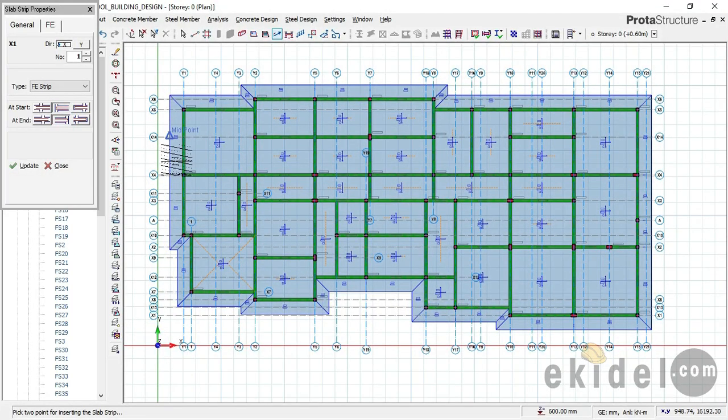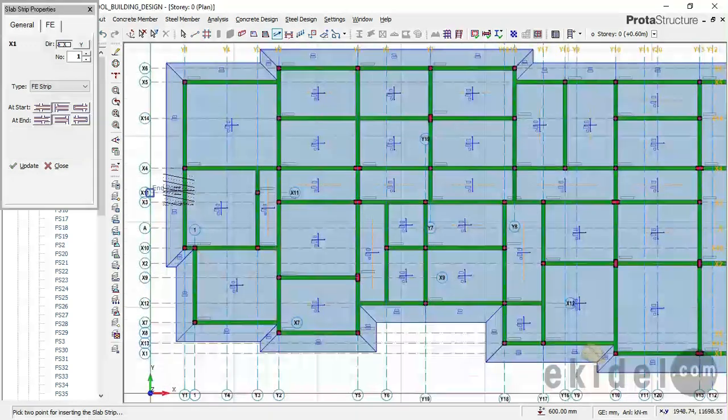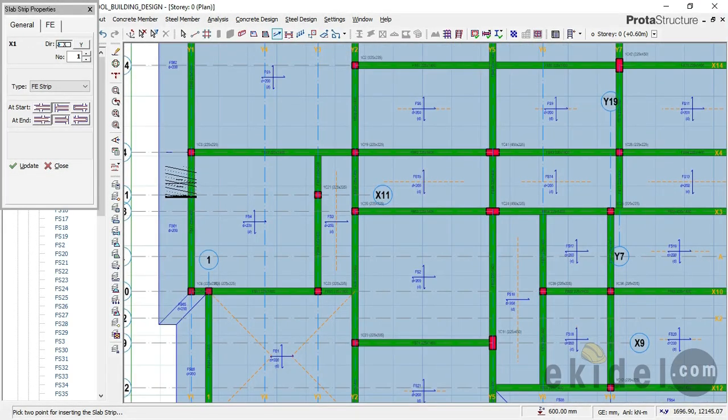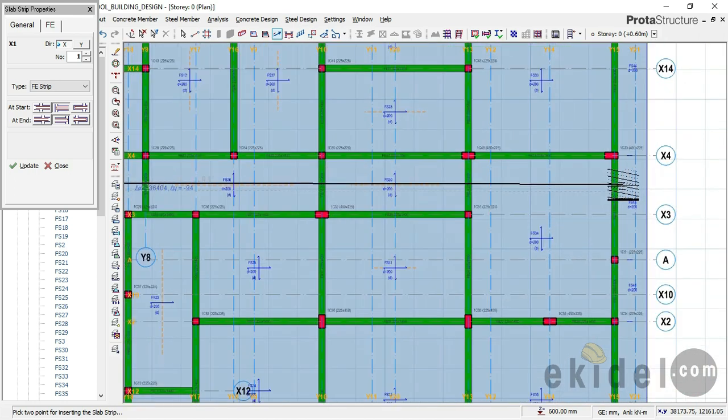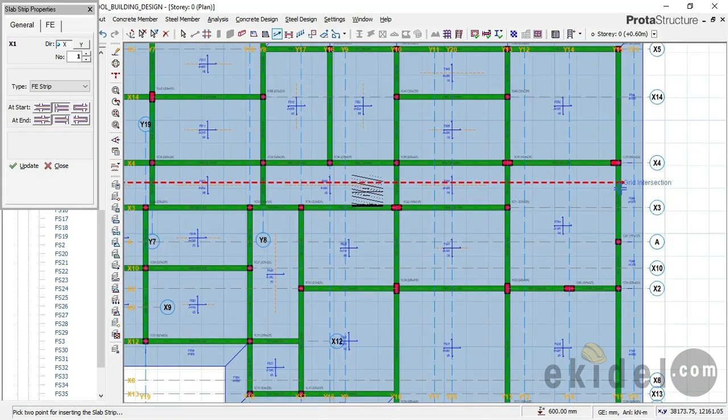Now, since this toe reinforcement is not the same thing as this slab raft reinforcement, and since they are at the same level, that means they will not detail the two together. So I'll have to start my cuttings of the slab detailing from this point and not at this edge here. So I'll quickly start from the very point once I pass this beam here. I'll click at this point just now and then go over to the next point since I'm cutting X direction, and then hold my control key to make my line straight and click at this point here. Okay, so right now I have cut my X direction.